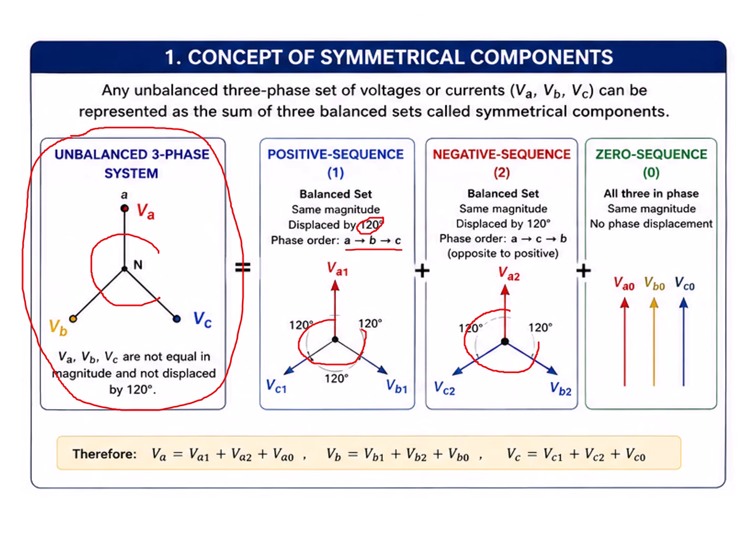The third component is what we call the zero sequence, and the zero sequence is like a DC component. The zero sequence of all phases, that means phase A, phase B, and phase C, have the same magnitude and the same direction. So equal magnitude and equal direction. Whenever there is an unsymmetrical fault, we can convert the asymmetrical phases into three sets of symmetrical components.